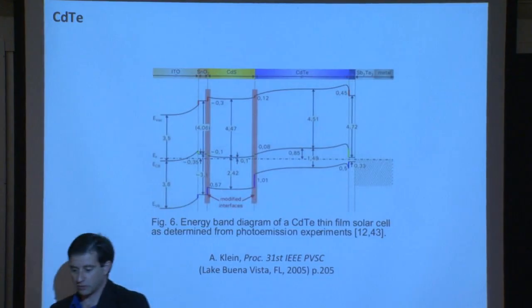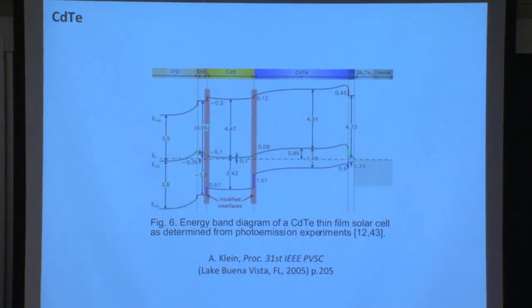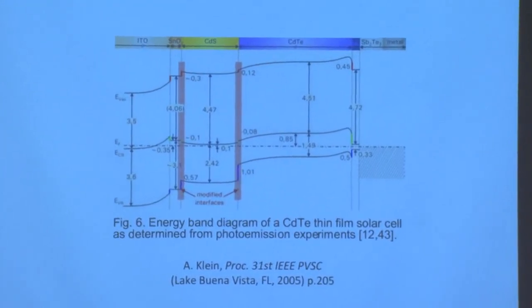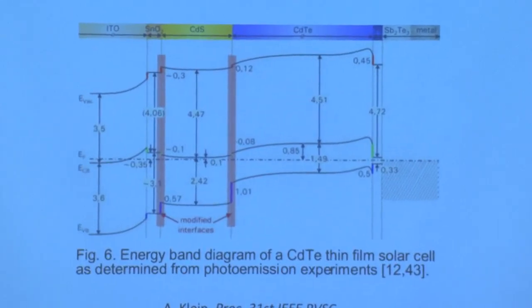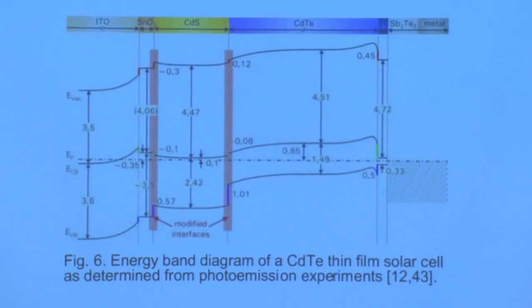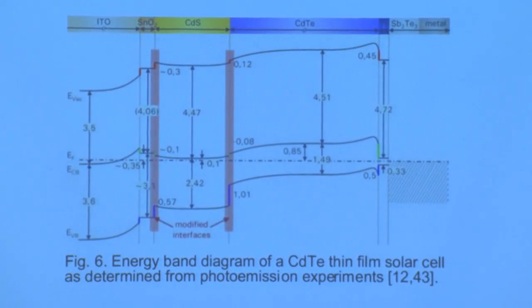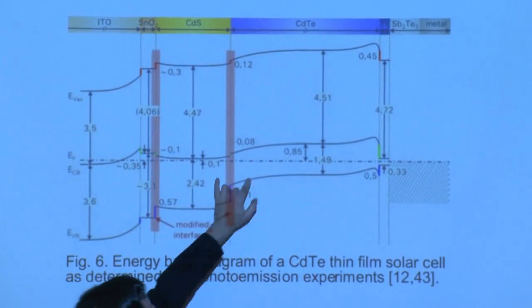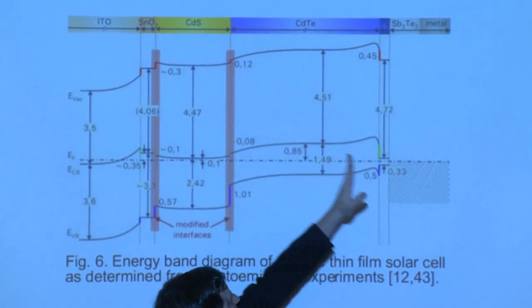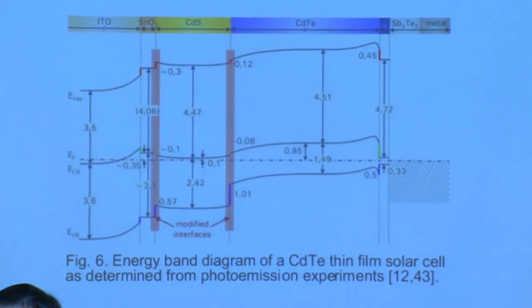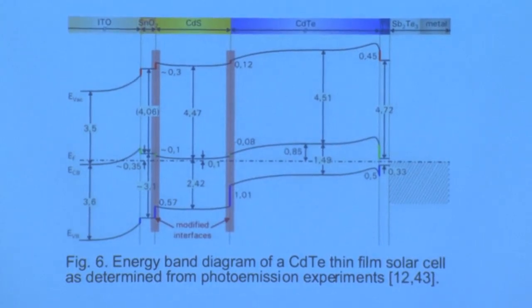Whereas in crystalline silicon, we had the band bending right near the junction region, so right within a few hundreds of nanometers, maybe a micron away from the junction, and the device was 100 microns thick. So we had approximately 100 microns of this flat band condition, at least in the dark. Here, we have band bending extending an appreciable percentage of the total thickness of our device just by virtue of the fact that we have such a thin film.